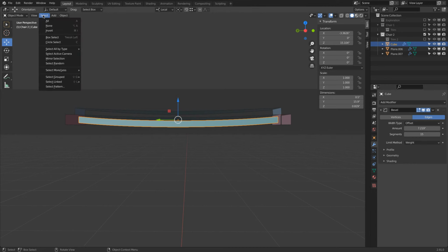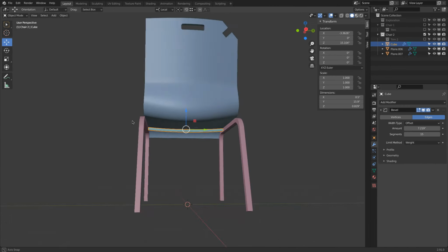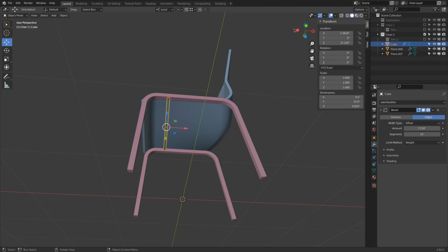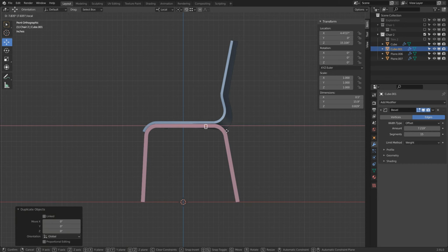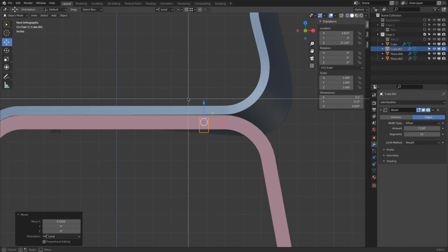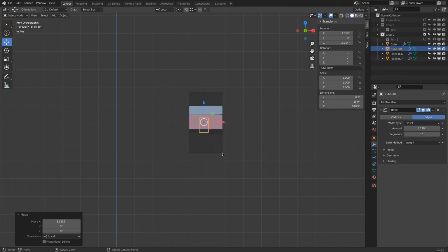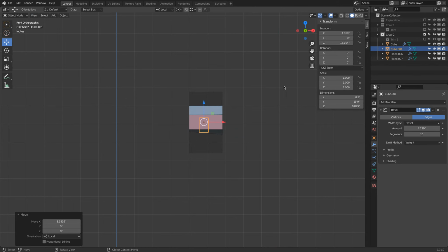Very good. Then we can go to View, View Region. Click on this so we get out. Then we can go to this view, Shift D and Escape. Bring this over to here. Zoom in. Alt B is the command for the region clip, or you use the menu.